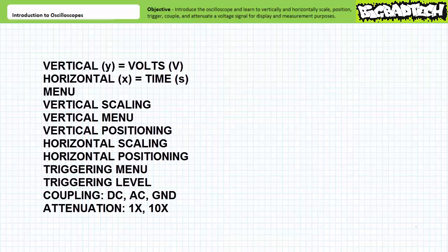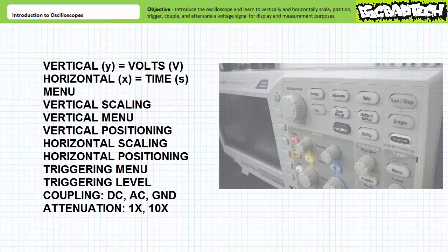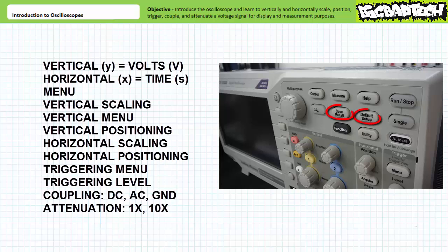This is often a task of simply walking through this list and figuring out which aspect, vertical, horizontal, positioning, triggering, coupling, or attenuation of the waveform under inspection is distorted and rectifying it. Hopelessly tangled scenarios can also be remedied by restoring an oscilloscope to the default or some pre-established standard setup. It may be lab standard operating procedures to begin and end each lab with a given condition.